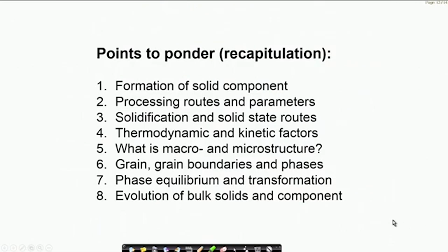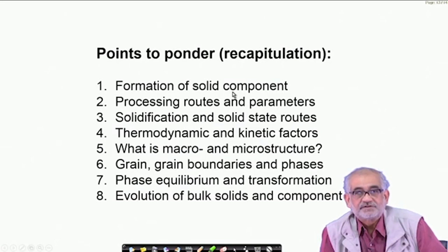So what is important is that we must appreciate the value of understanding microstructure. So why is microstructure important? Because we are dealing with solid components, and the properties of solid components would greatly depend not only upon the composition but the evolution of the microstructure. In order to understand the evolution of microstructure, we must understand the processing routes that we followed, and the process parameters that actually affected the various thermal and mechanical conditions during the processing.